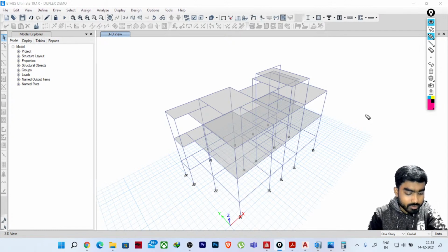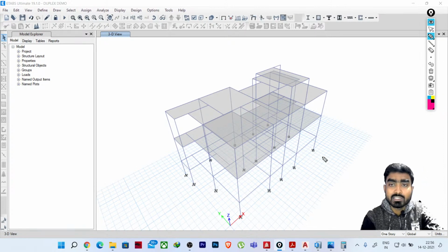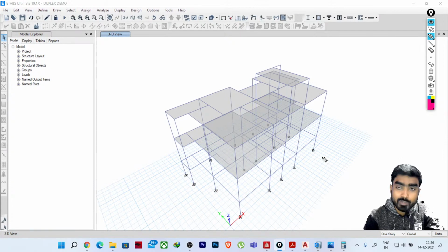No. Why should you make it over reinforced? When you have over reinforced sections, you will find brittle failures, right? You will be having cracks at a very initial stage. So you should not design with over reinforcement, obviously, to make it ductile. So that's why you need to check what reinforcement percentage you are getting. If you are getting column reinforcement percentage of 3%, 4%, this is over reinforced, right? Though the code allows up to 6%, we should not go with 3% and 4% in a column, which is very uneconomical.